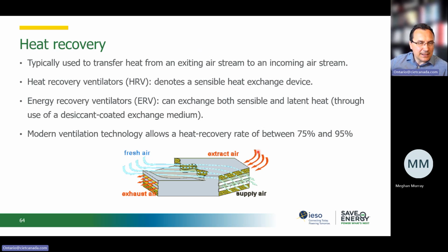And that heat is transferred to the fresh air in this heat exchanger. The type of heat exchanger will define if we have a heat recovery ventilator or an energy recovery ventilator. The difference, as I mentioned, being the latent heat.